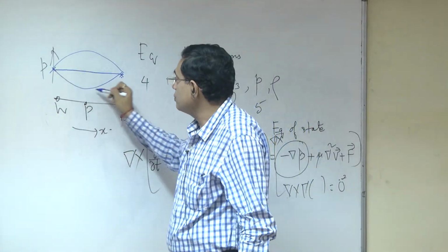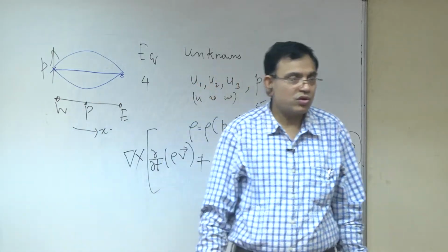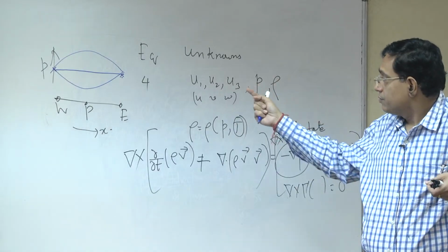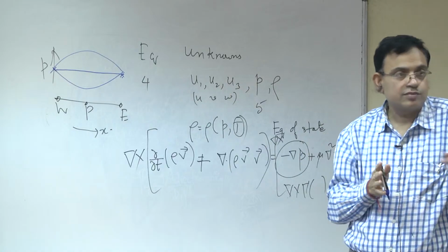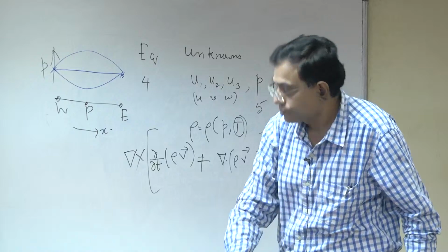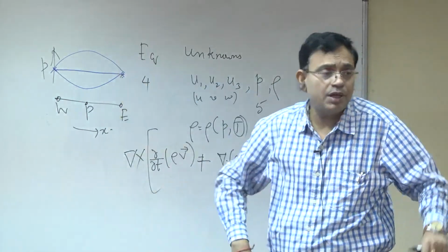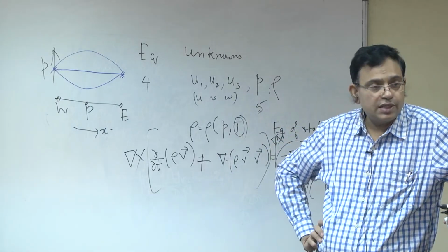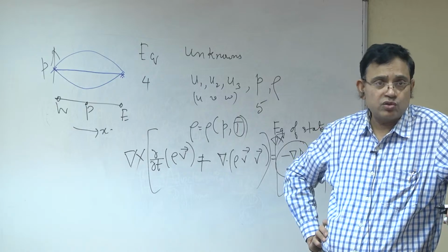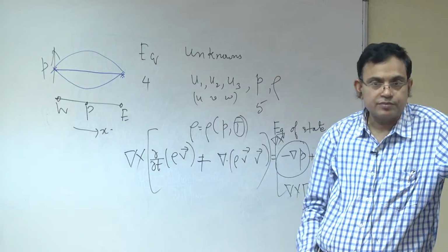Now, this is actually a non-zero pressure gradient and this is also a non-zero pressure gradient, but this is not able to capture that. So, it can predict something which is physically unrealistic, because the value of pressure at the point P is nowhere coming into your picture, right. So, you need a remedy for this. How do you get a remedy for this? You also have similar points for velocity, because you have this velocity integration also very similar, like the pressure gradient, velocity gradient also the same. So, nowhere the value at capital P is influencing your solution. As if whatever is the value of capital P, your answer would be the same, but it cannot be like that. Your answer should be influenced by the value at capital P, right.